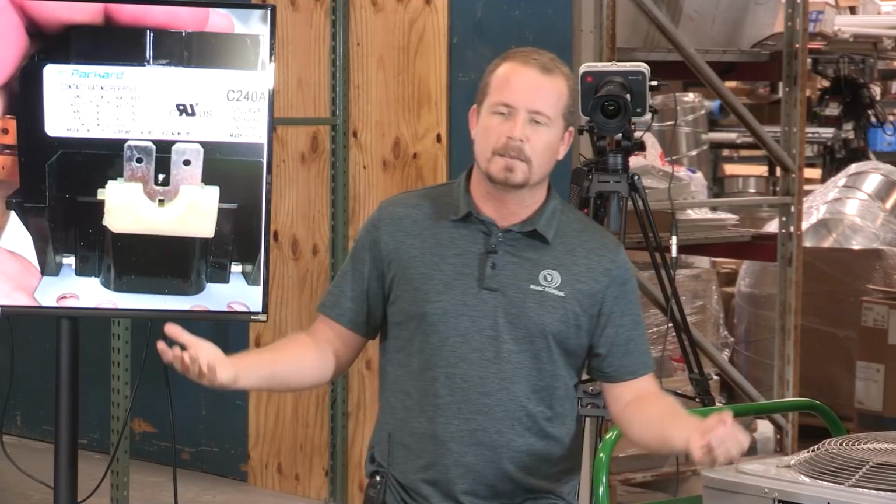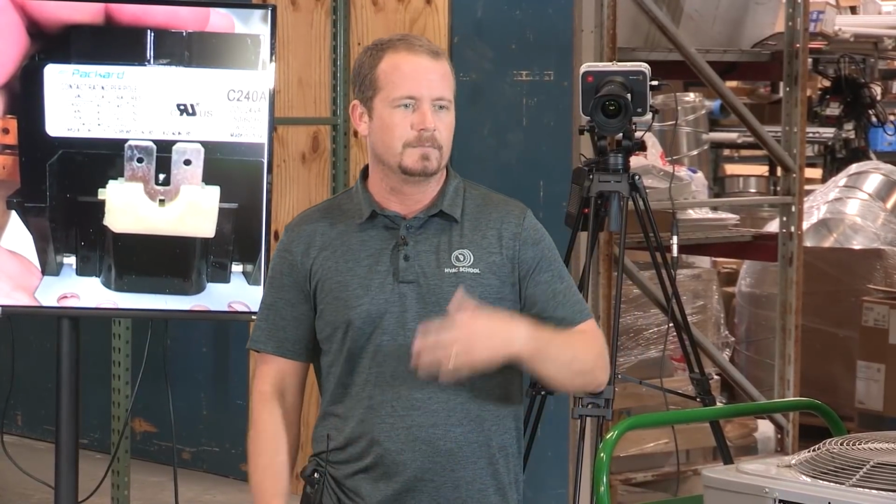Now, a lot of people just say, hey, it's no problem, just run number 4 wire and everything's fine. Sometimes you're talking about applications in multifamily or commercial where there might be multiple floors, and it could be a major deal. Sure, if it's just a matter of running a new whip to a breaker panel, well then fine, who cares? Put as big a wire in there as you want, so long as the termination points are designed to accept that wire.